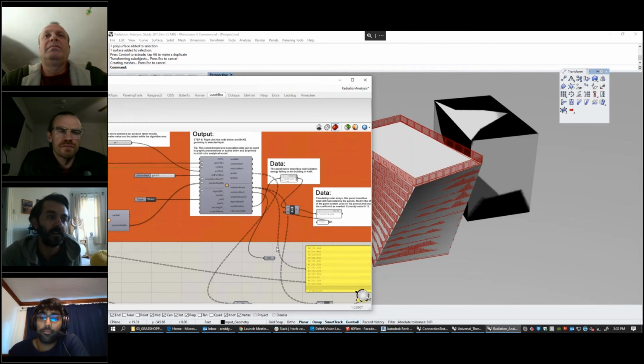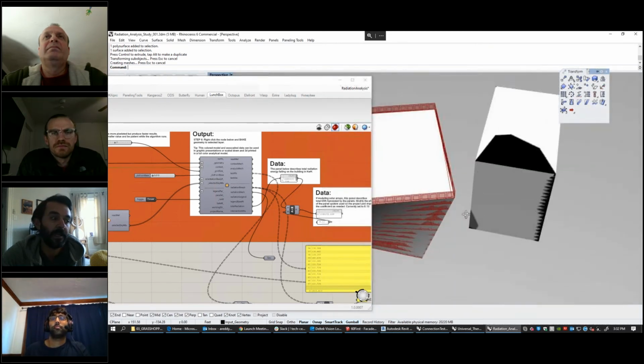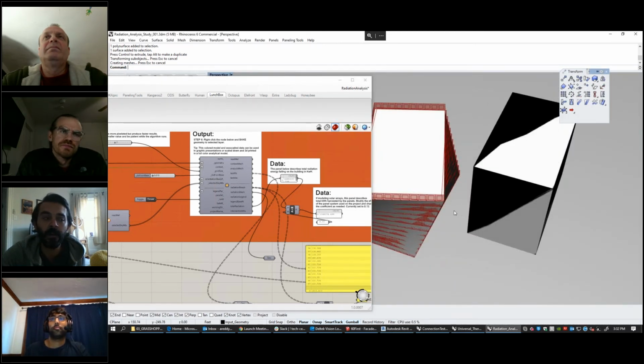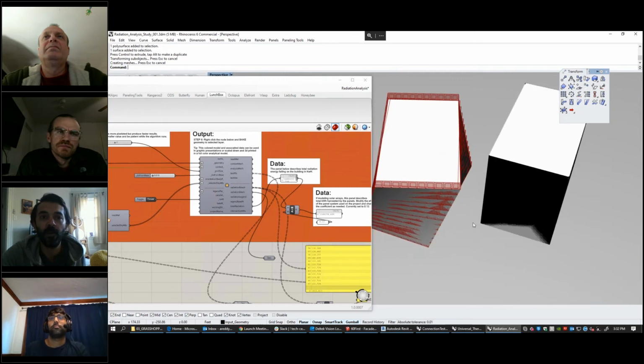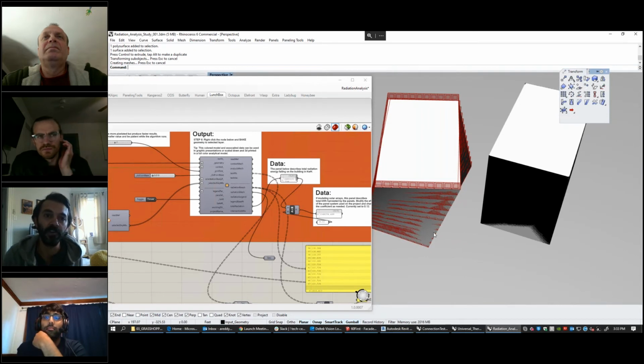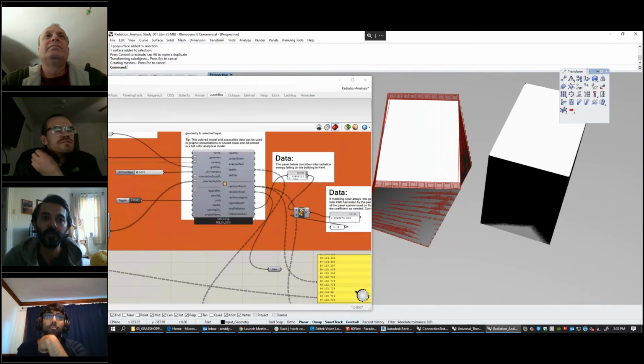We were just doing a study the other day where we were looking at sun on a ground plane and trying to hit a target percentage over the course of a duration of time on a very specific day. That storyline was shared with me, and then we were able to take one of these existing scripts and build it out to find percentages across an average sample, which is what Anish was showing with those sample points, using all the stuff that comes right out of the back end of one of those Ladybug components.